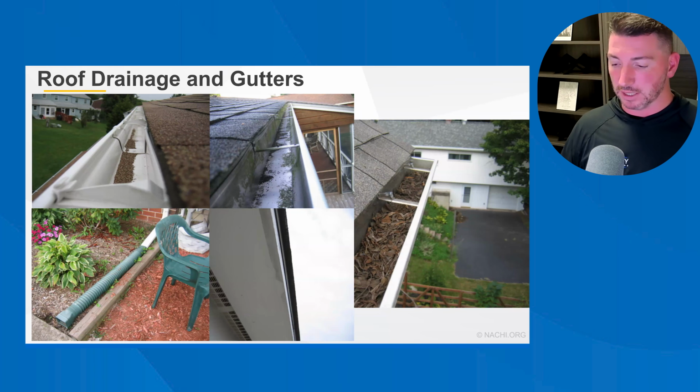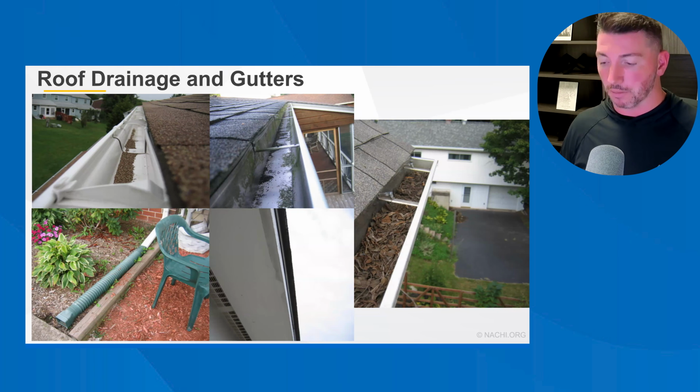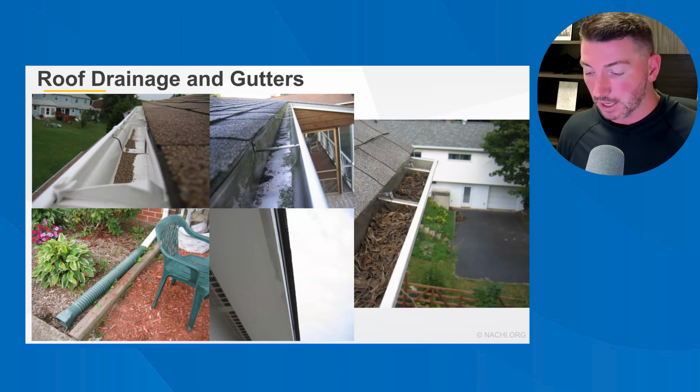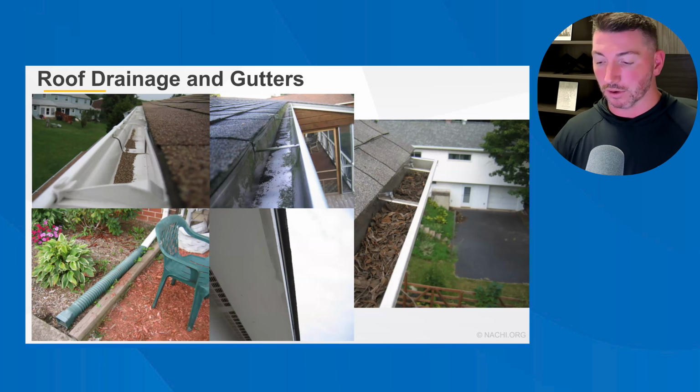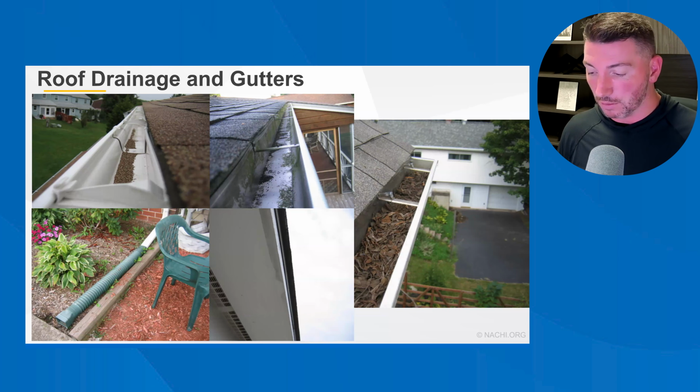Roof gutters, downspouts, and leaders or diverters form the initial components of a drainage system for the building and site. A proper design of gutters and downspouts for water-shedding sloped roof systems should be addressed during a roof inspection. Common problems with guttering are associated with installation and maintenance. Home inspectors can check if properly sized materials are being used, if guttering is appropriately sloped towards adequately sized downspouts, and if discharge is directed away from the building's foundation and perimeter. Discharge water at the building's inside corners should be avoided. Some local stormwater codes may require special filtration treatments of roof water runoff.